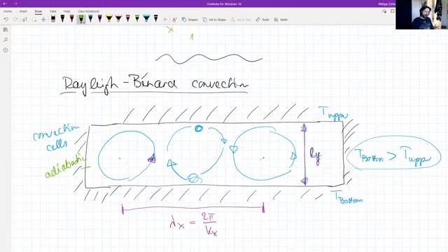equation. And then you also need to implement the buoyancy forcing as indicated in the manual as well. So you need to have a buoyancy force in the vertical direction that depends on essentially the local temperature. As I was saying, the temperature changes the density, and the density then gives rise to a buoyancy force.